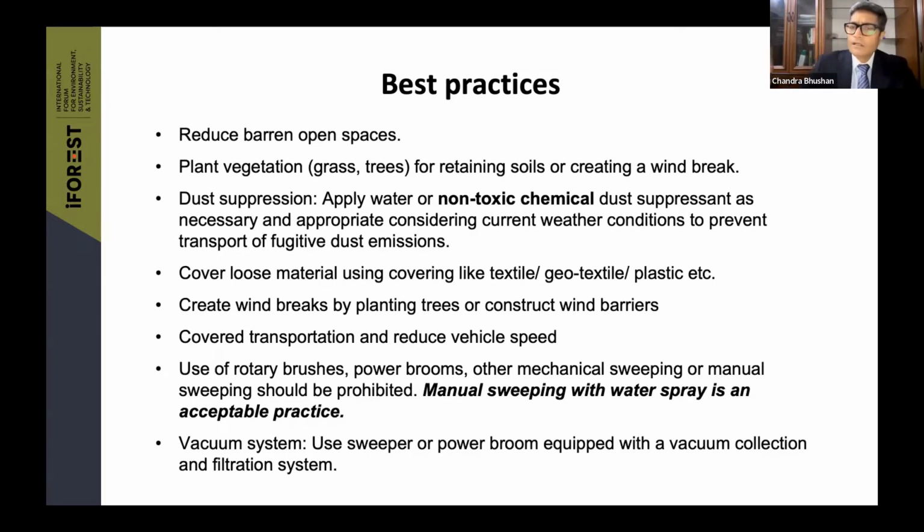And therefore, as far as the municipality is concerned, please ensure that there is no loose material at a construction site, if you want to really reduce dust emission from a construction site. For larger sites, you will have to create windbreaks. And this practice is now becoming quite common in big cities, where steel plates, steel sheets are being used as a windbreak, or trees are kept as a windbreak.